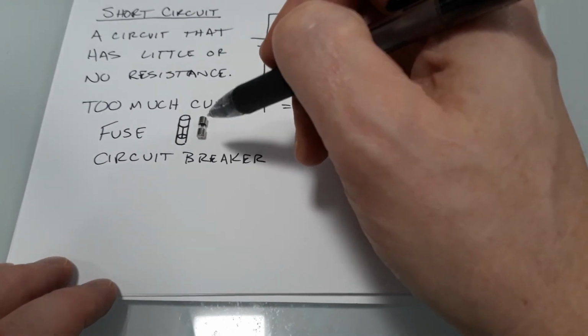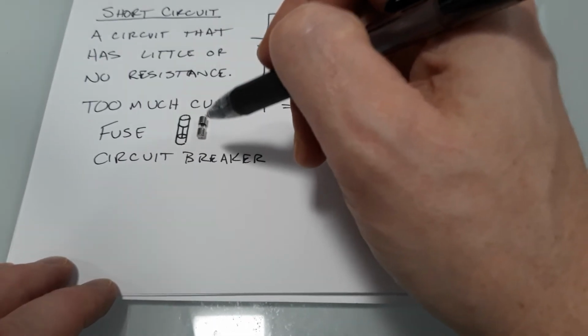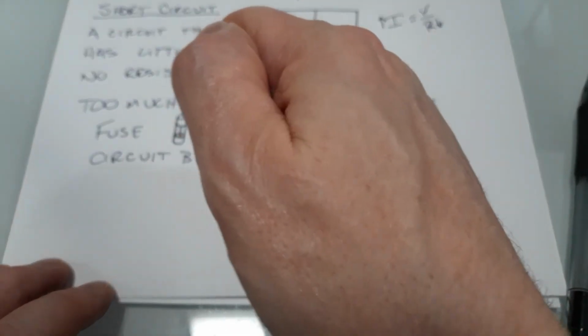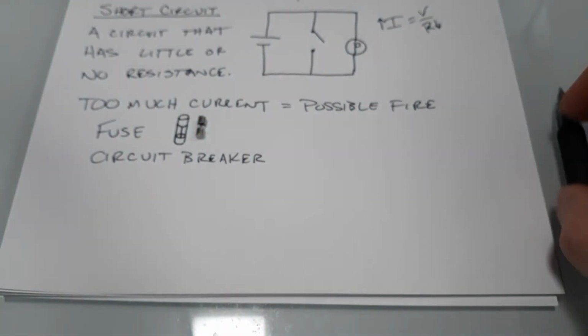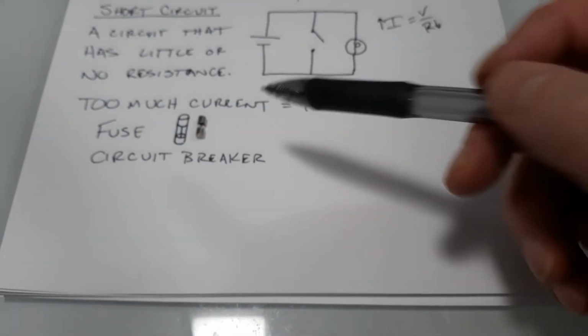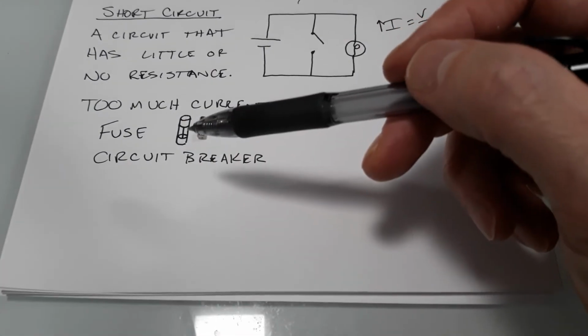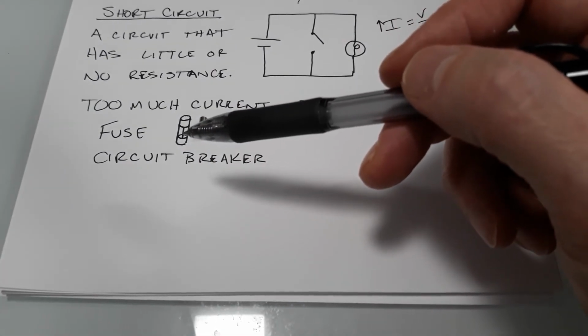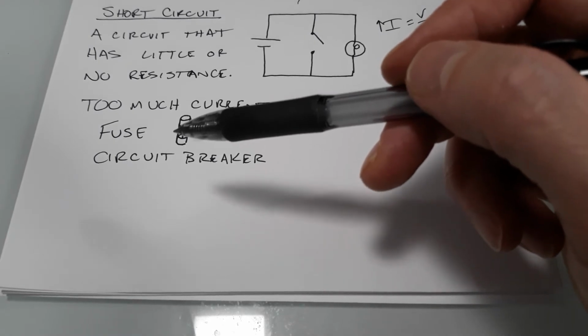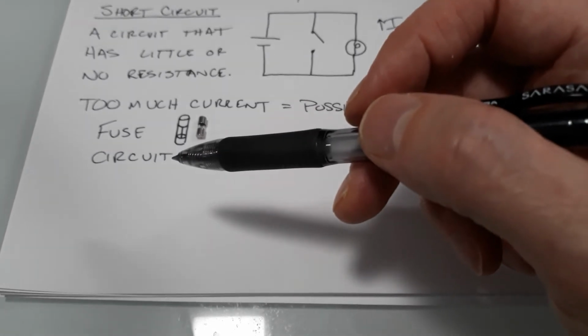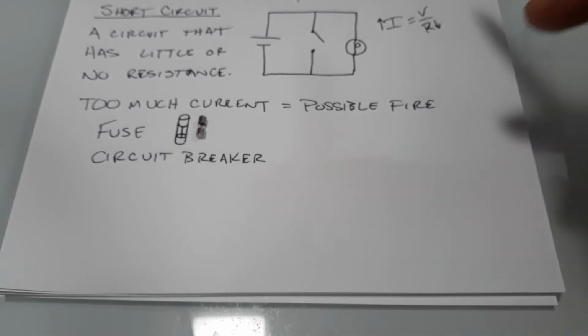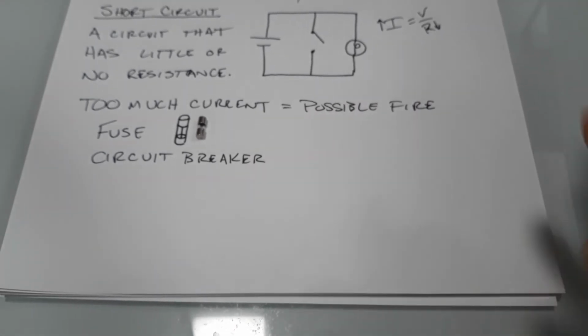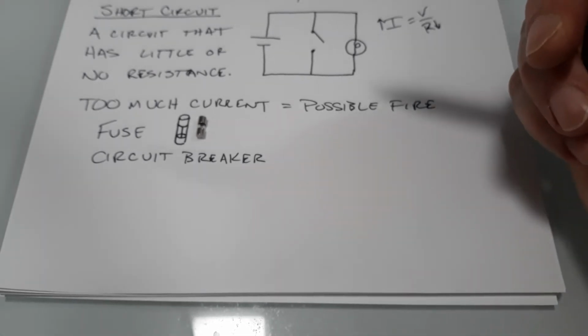And the reason why Christmas tree lights have a fuse inside the plug, I'm saying when you plug into the wall, that part that's in your hand, if you look at it closely, you'll probably find there's a little panel that opens. And inside of it is one of these guys. Now, it depends on the lights. Not all lights will have them, but most of them should. And the reason is because we want to be really careful not to put too much current through Christmas lights, because if they get too hot and they're wrapped around a dry, dead Christmas tree, of course, they're going to cause a fire. So very important that those things are not allowed to ever get anywhere near a large current in there so that they don't cause a fire.